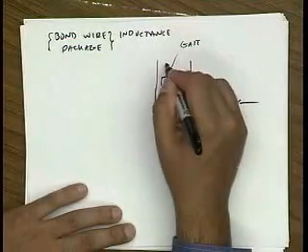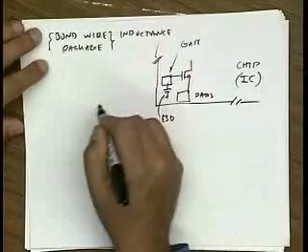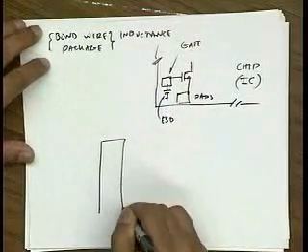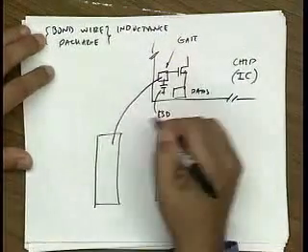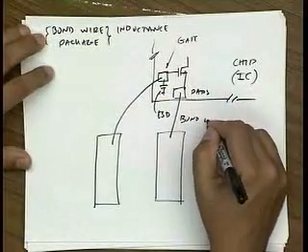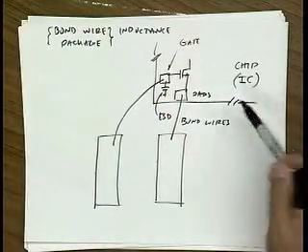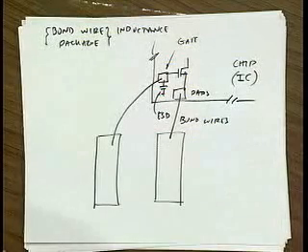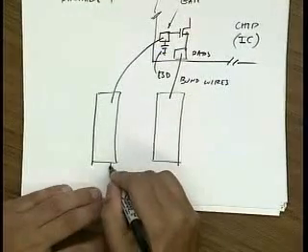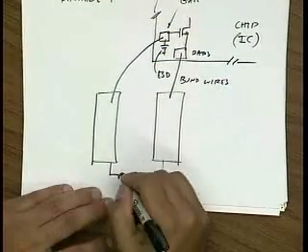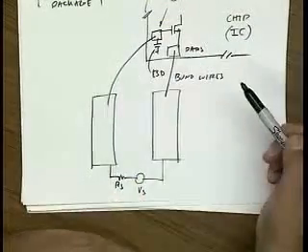And then I have to house this chip. So this is my chip. This is the IC, integrated circuit chip. I have to basically put this into a package, and even this is not to scale. The package means that I have to use bond wires to connect from the pads to the package leads. There is a technology called chip on board where you actually directly bond to the board, but that's not as common. It's more common to go into a package. Okay? And so this is where I connect up my source. So it has to drive these leads and then these bond wires and then the transistor itself.